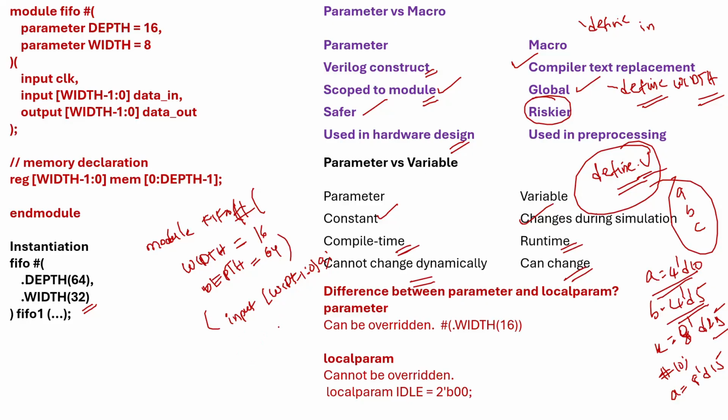Then after closing the parameters, brackets close and a semicolon means my module parameters are closed. Below that comes localparam. The keyword is localparam, which I will utilize. Then I use the local parameter address width there.